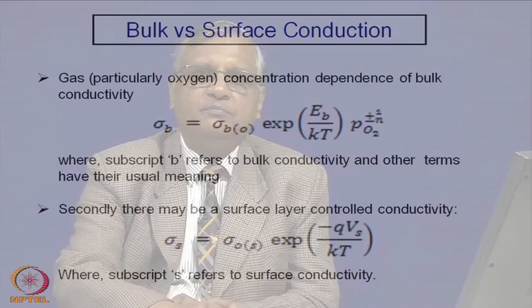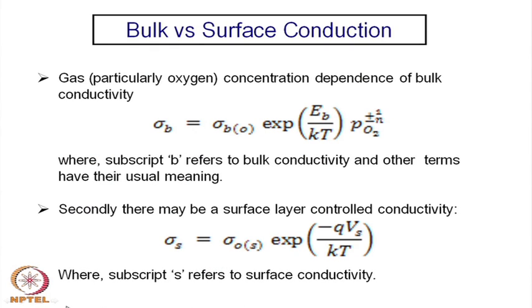So, that is a very basic principle, but that is so far as the bulk conductivity is concerned, when we are not considering the adsorbed layer or the surface layer. If we are talking about the surface layer, then there is band bending, as we have seen, and some surface states are created in the energy band diagram, and as a result there is an enhanced barrier height.